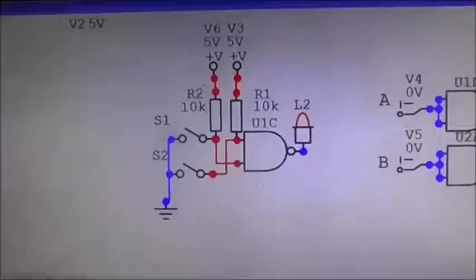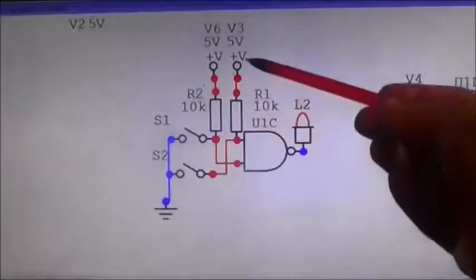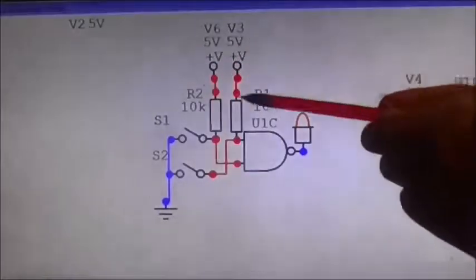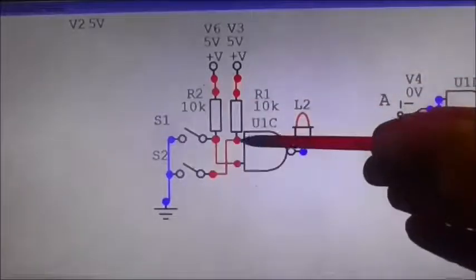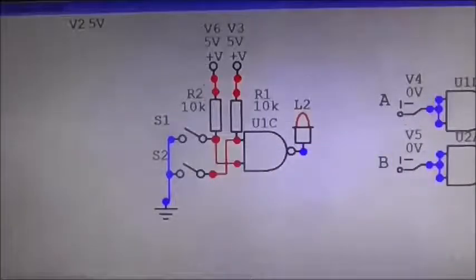And carrying on then, what we've got here is something a bit esoteric, and it's called an interrupter. What we've got is two pull-up resistors, each connected to a different 5-volt supply, and that 5-volt supply will be coming out from a subsystem somewhere into this thing, and they're ensuring that the two inputs of the AND gate are kept continually high, except when a switch is flipped, in which case it goes low, and that will send a signal to another part of a subsystem.